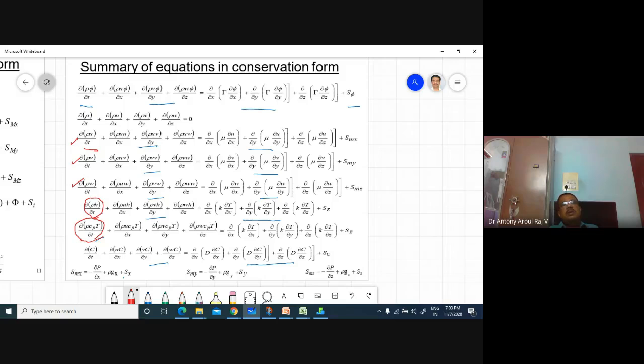So going from zero velocity to a particular velocity, that is flow transients. Similarly, when you switch off the air conditioner, the fan will not immediately go off. Because of inertia, it will rotate for some time, so your velocity will drop slowly to zero. So like energy, you will have flow transients at the beginning of starting the air conditioner, and similarly while switching it off. In between, you will not have flow transients, so all these terms will become zero. While running, these terms will become zero. Now you should understand the significance of this term.